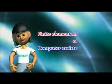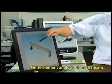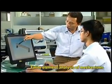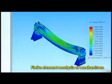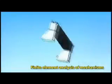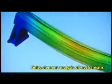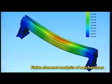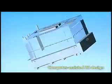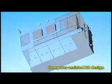Finite element analysis of mechanisms and 3D computer design. To ensure a machine has a high level of accuracy, software tools can be used in the design of a linear motor platform to analyze the strength and deformation of components. This can enable places where deformation may occur to be reinforced, improving the platform's flatness, linearity, and overall accuracy, and achieving the goal of optimized design. A computer-assisted finite element analysis is usually employed to achieve this goal. Computer-assisted 3D design can also be used to discover interference issues early on.